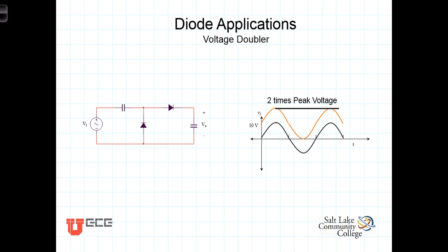Let's look at the circuit and see how this might be. You'll notice that this circuit has 2 parts. This first part is the same circuit that we saw as the DC restorer, or this first part adds a DC component. The second part of this circuit is the sampler.